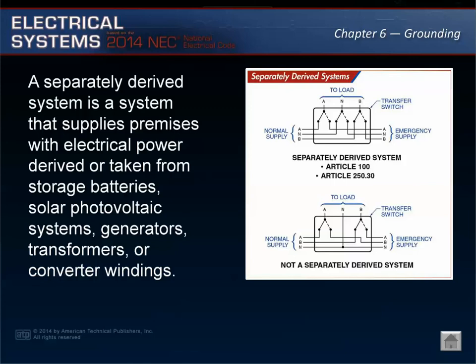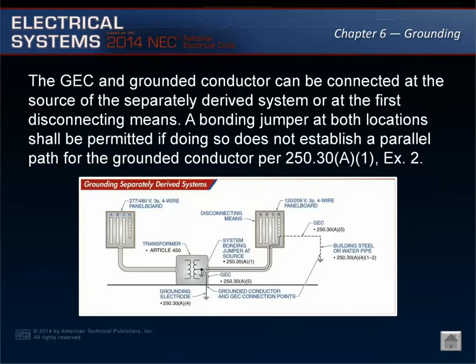If the grounded conductor is solidly connected, then there is not a separately derived system. Ground references cannot be transferred through windings of any type. The grounding connections that were in place for the service must be re-established.